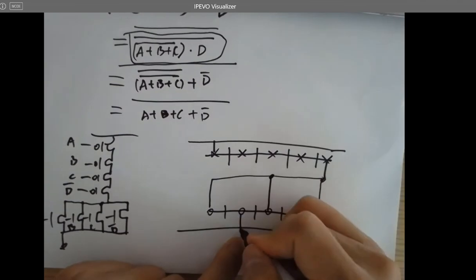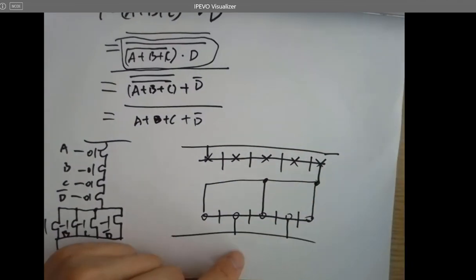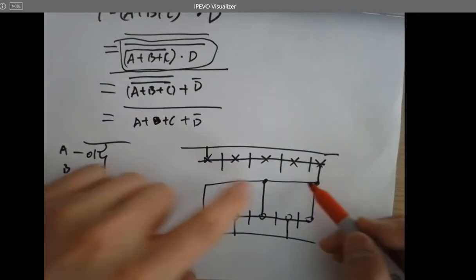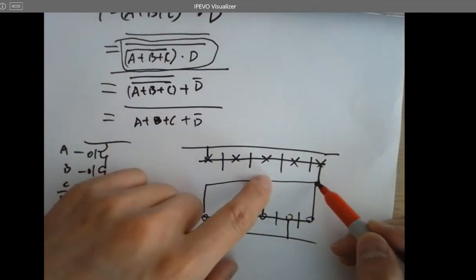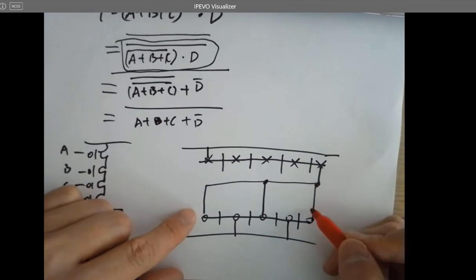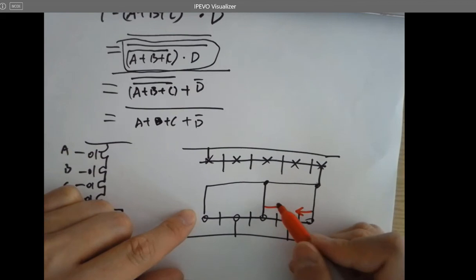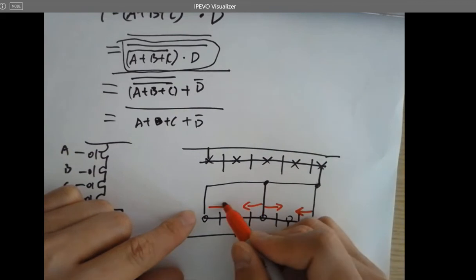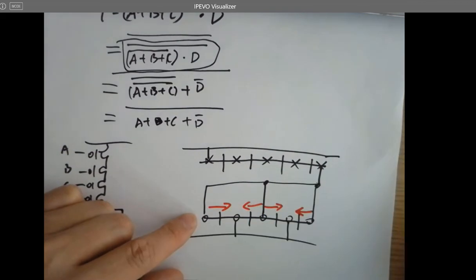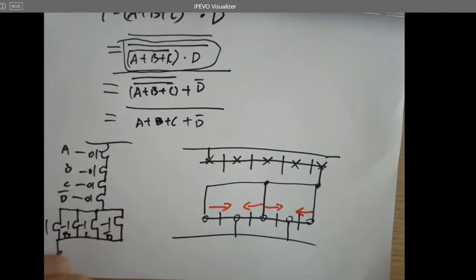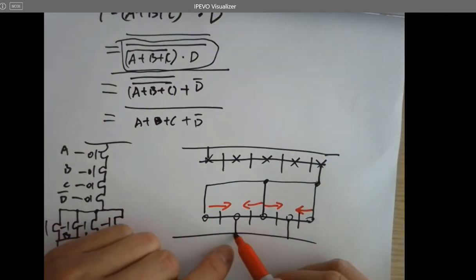Yeah. Why? So signals are being introduced from this one node. It's being split into 1, 2, 3, 4. So 4 NMOSes are in parallel. And that output is merged into this node, which is ground.